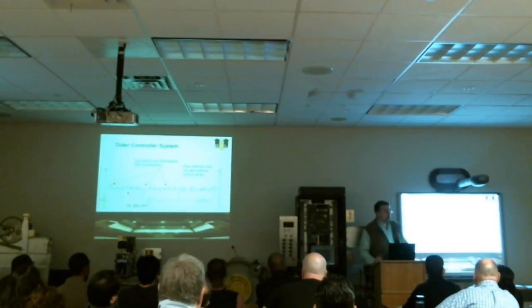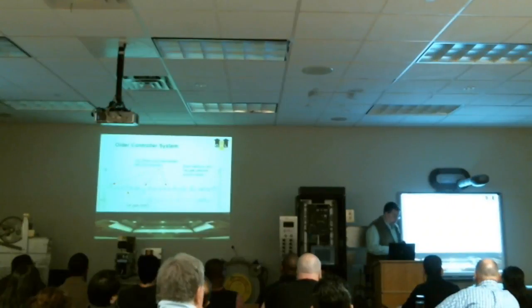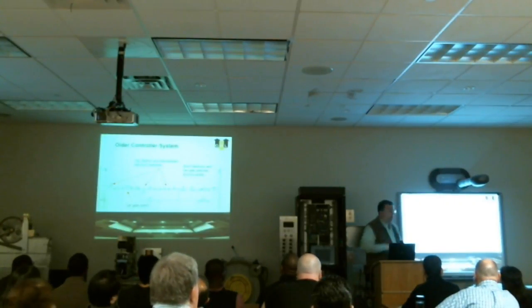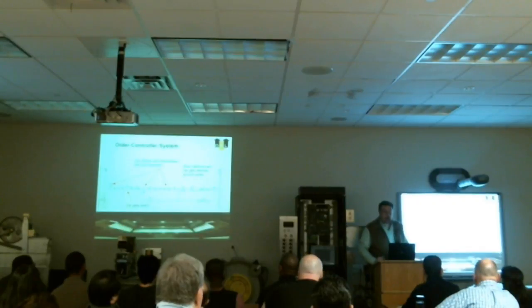But what would that do? Well, that tells the elevator controller that, hey, my doors are closed even though they are not closed. Exactly. And this is where a lot of accidents have occurred, where the elevator would run with the doors open, where people have gotten hurt and killed over the years. So this is the way the old system used to work, monitoring all of them in one shot. It didn't care if one, both, or all of them were bypassed. Once it saw everything was made, it said, go ahead, you're allowed to run the elevator.